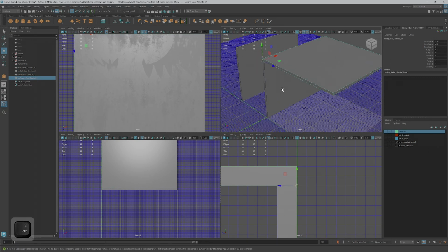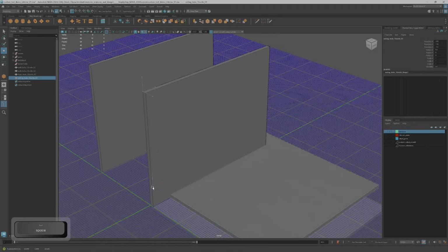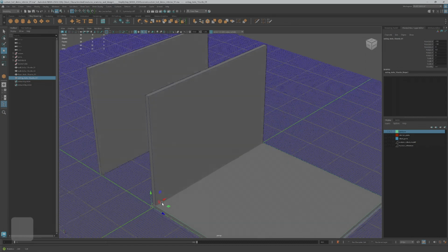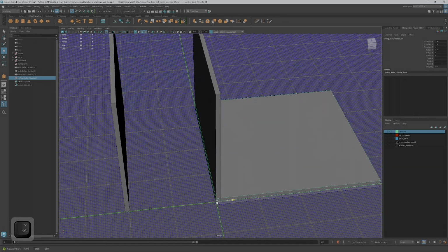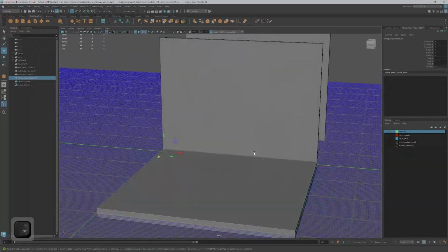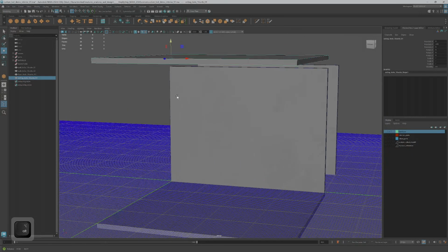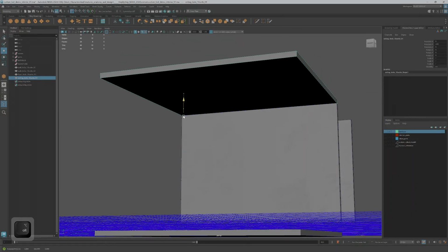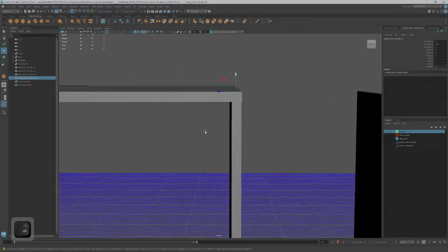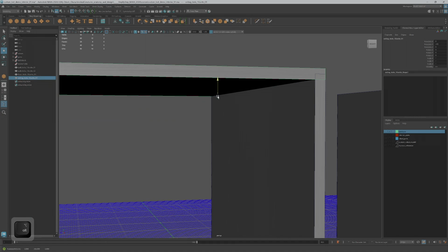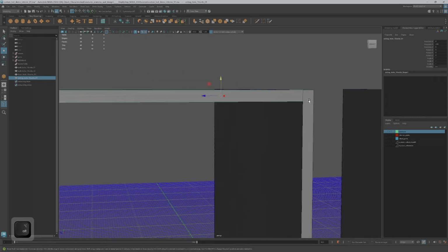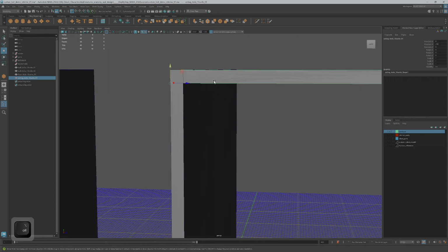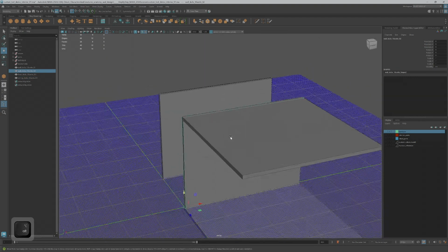So what I'm going to do for right now is I'm going to drag it down back to 0, 0, 0 world space, just like that, and then freeze it, delete its history as well, and then I can just snap and bring that back up, and it should snap right into place to the top of the wall. Now, if you want to push this and pass it through down a unit or two, that's okay because only this part would be Z-fighting. That's where the faces of the wall and the faces of the ceiling intersect and share space right here. But you'll never see that, so that's okay. So that's what I'm doing for that for now.